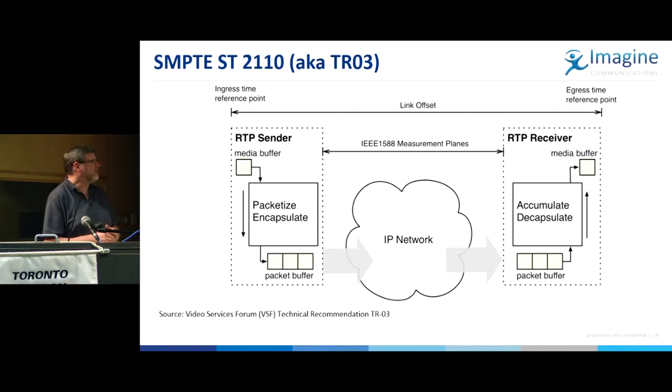Again, using that same technique, when the signal is received in the transmitter, we mark the timestamp. On our playout, because the devices are locked together, we just have to decide how long we want our playout delay to be and line up all the samples. So that's another way we can use this timestamp.